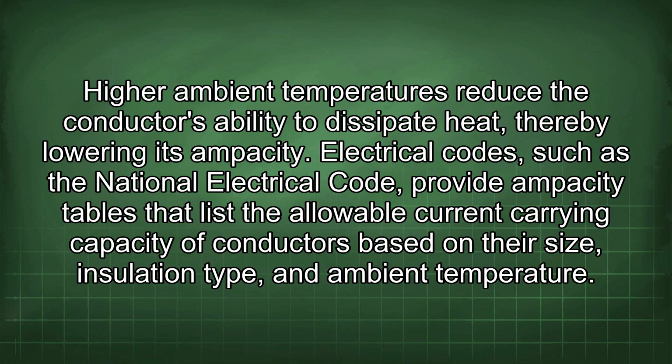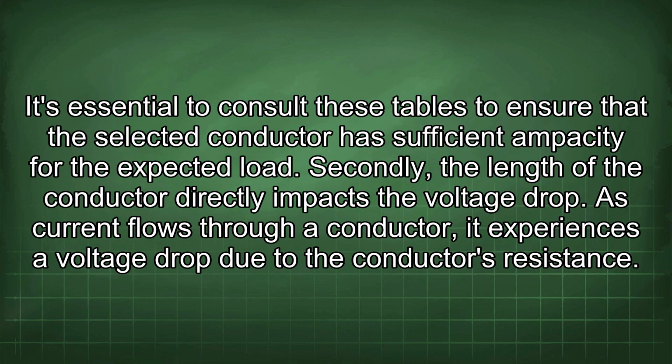Electrical codes, such as the National Electrical Code, provide ampacity tables that list the allowable current carrying capacity of conductors based on their size, insulation type, and ambient temperature. It's essential to consult these tables to ensure that the selected conductor has sufficient ampacity for the expected load.